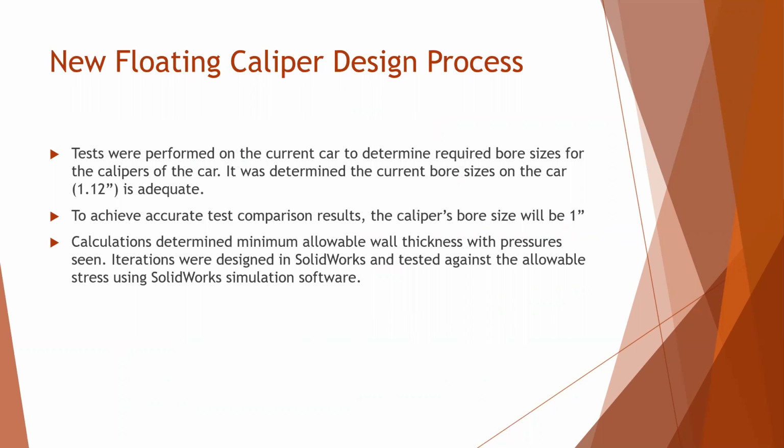In the new floating caliper design process, tests were performed on the current car to determine required bore sizes. This was done by dragging the car and seeing what force allowed the wheels to be dragged while also being locked up. It was determined from this testing that the current bore size on the car of 1.12 inches is adequate. To achieve accurate test comparison results, the caliper's bore size for the caliper design in this research will be 1 inch, because we also have 1-inch Wilwood PS1s in the shop that can be compared to for numerical analysis.